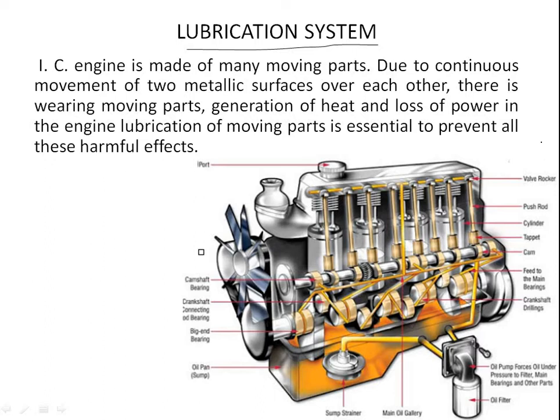Lubricant enters into the gap between the cylinder liner, piston and piston rings, thus it prevents leakage of gases from the engine cylinders. Fourth one, cleaning effect. Lubrication keeps the engine clean by removing dirt or carbon from inside of the engine along with oil. Fifth one, to absorb shocks between the bearings and the other parts. And sixth one, to clean surfaces by carrying away the carbon and metal.